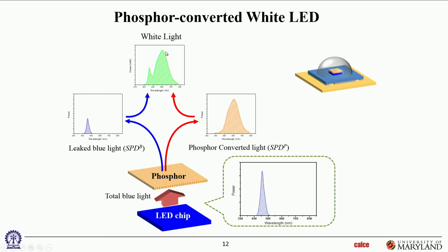It's bimodal. That's the nature of all LED light. You'll find that it's a bimodal spectrum distribution. Depending on how much blue you're leaving in versus what percentage you're able to convert, the more you convert, the warmer the color. So you buy daylight white, you buy warm white, which is more yellowish, right? The daylight white has less conversion, more blue in it. The warm whites have more conversion, less blue in it, basically.